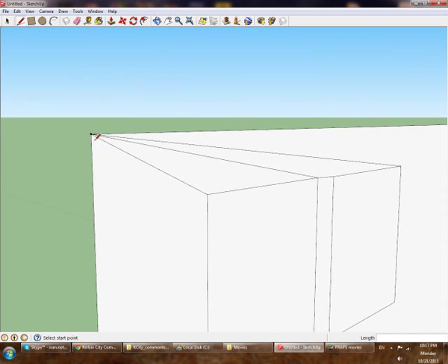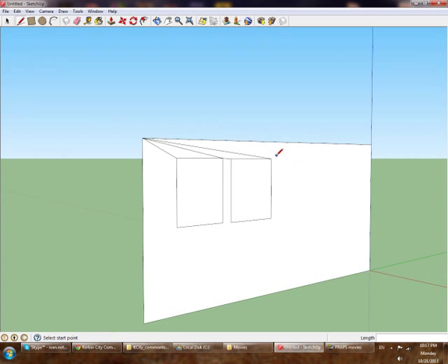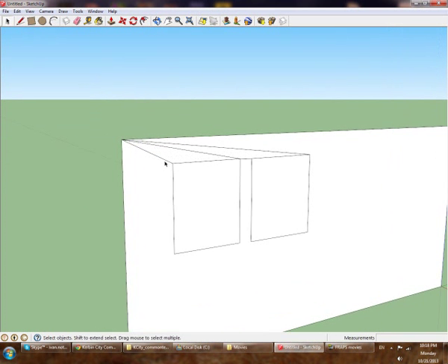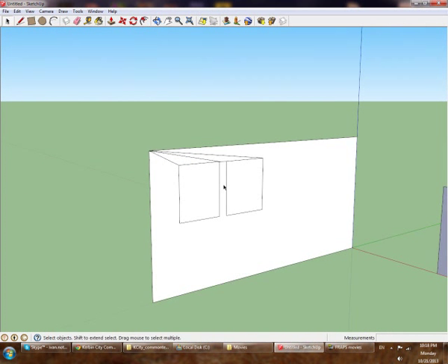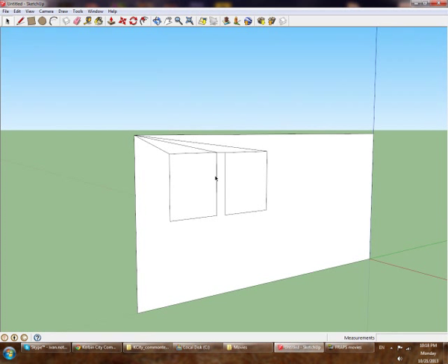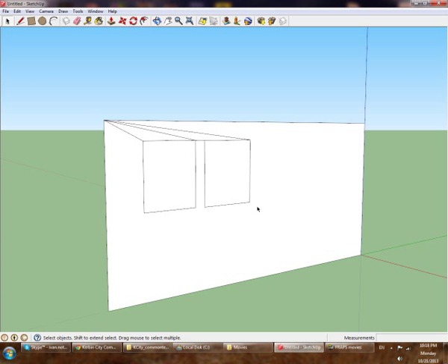You will have one vertex that has 5 lines in this case coming off, and now imagine if you cut it a lot of times. In games this is a very, very bad practice, because there's loads of problems that can happen out of this thing. So it's very important to know that you should always model in quads, which is a 4-sided polygon.